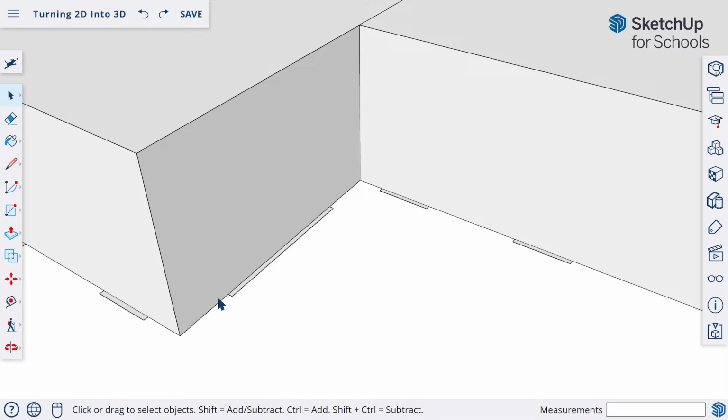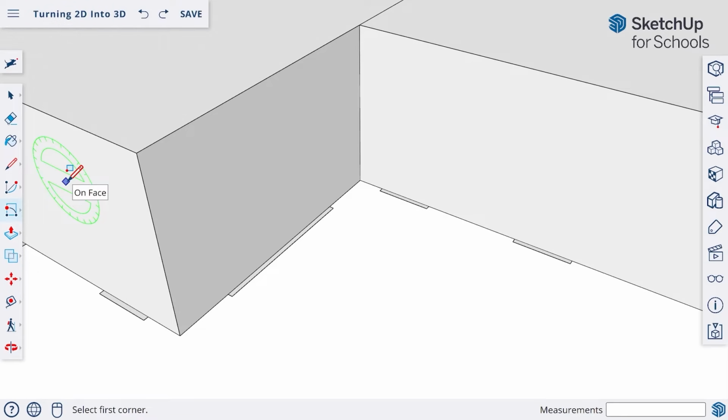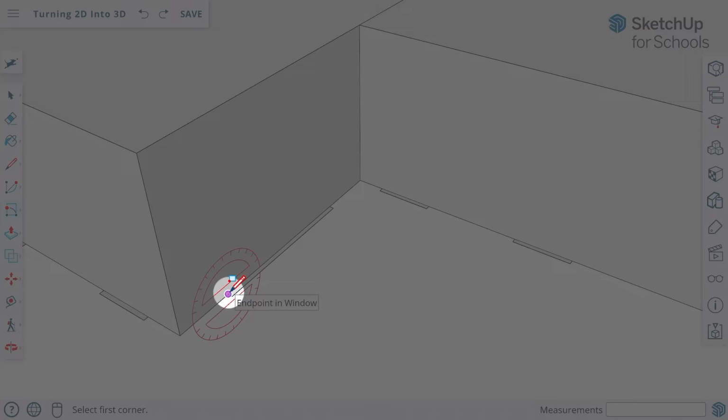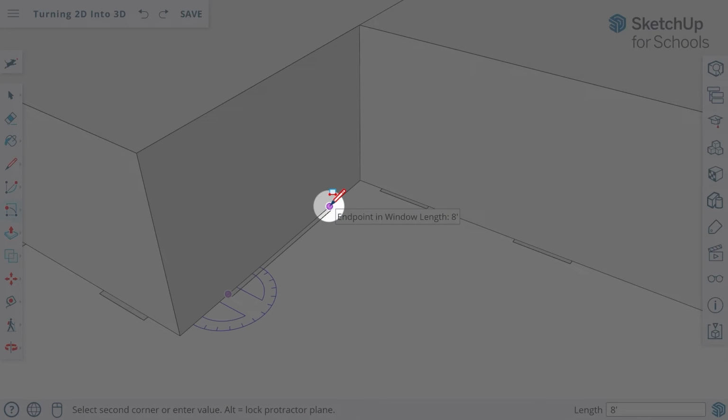To draw an opening for this, let's use not the rectangle tool, but the rotated rectangle tool, which is the second rectangle tool in the drawing tools here. This tool acts slightly different than the rectangle tool in that it is 3 clicks. The first click is on the end point for the first corner. The second click is at the second corner, which we can do here.